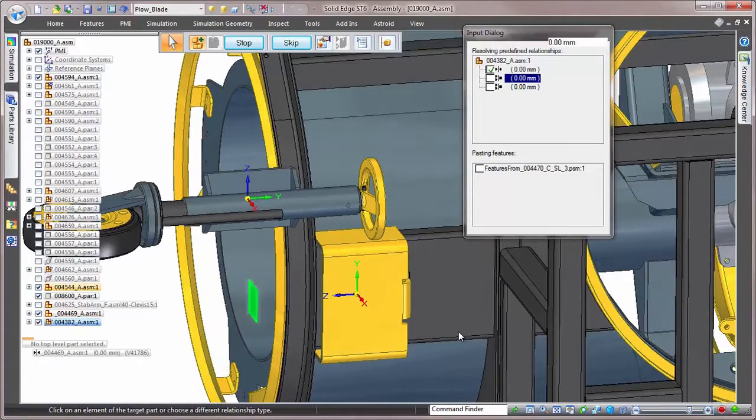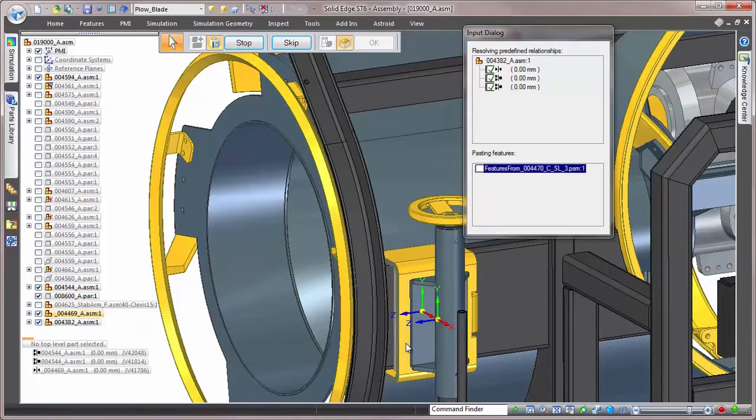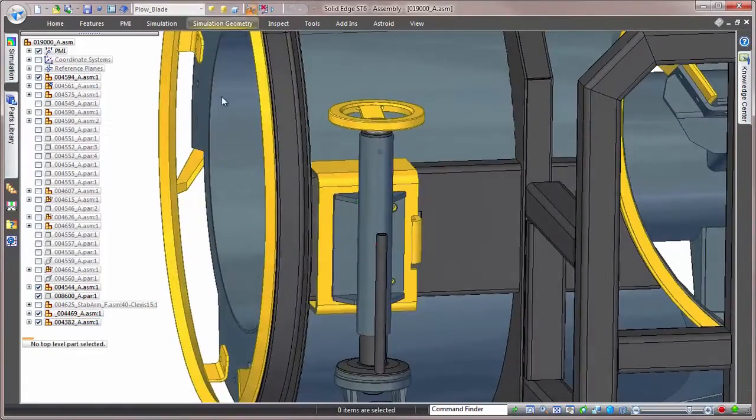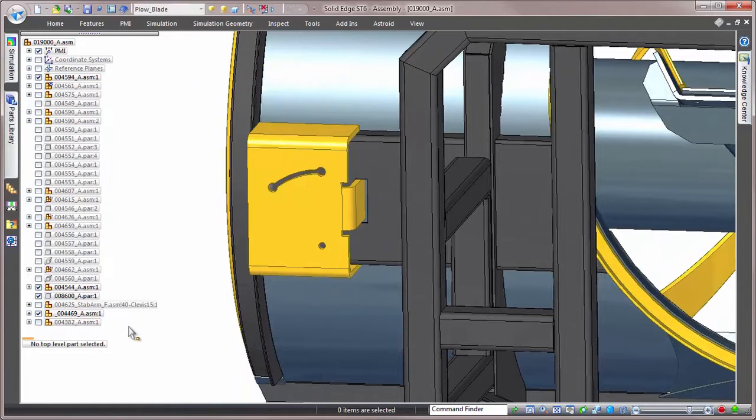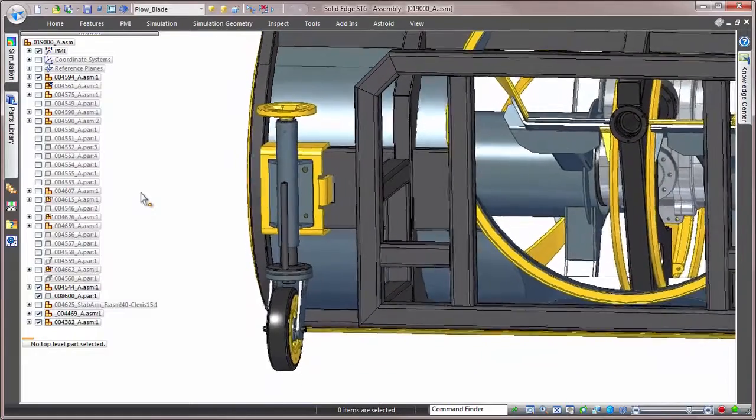that we just configured. A system library allows us to simply select the parts that we want our mounting geometry to be associated to, and Solid Edge automates the placement of the mounting features. No additional work from us, and our mounting slot and pivot point are perfectly placed.